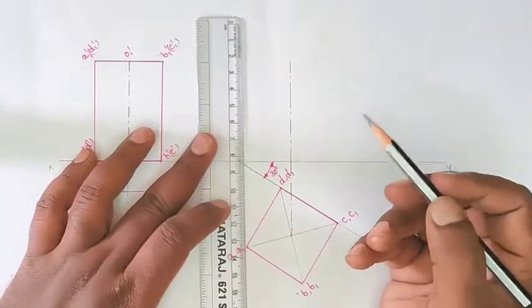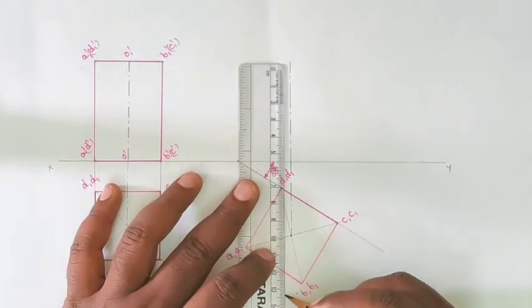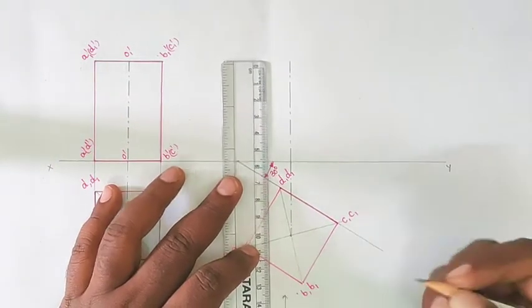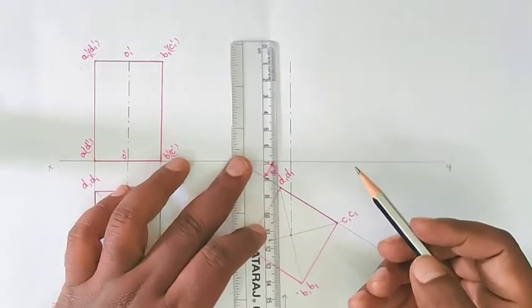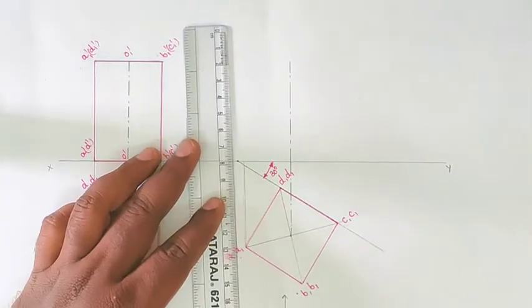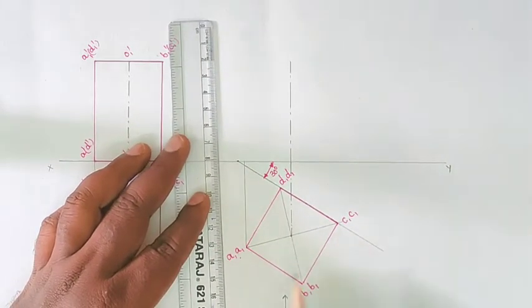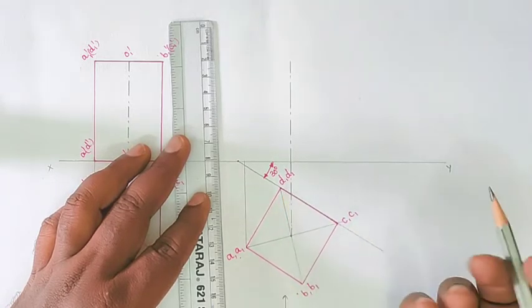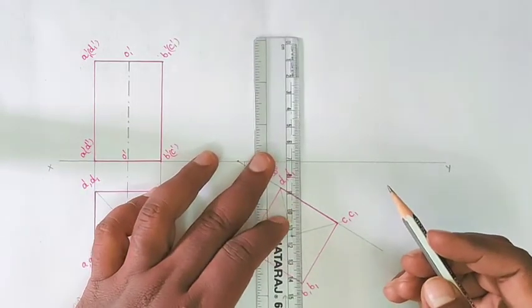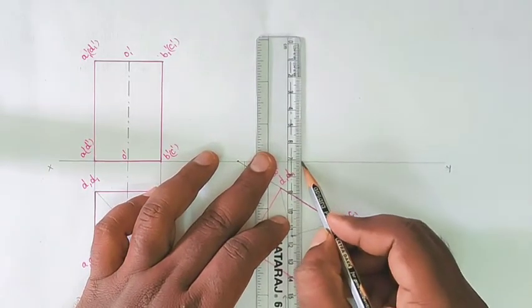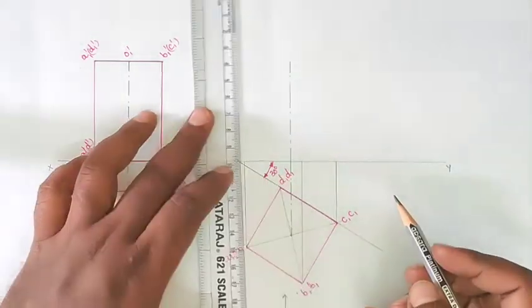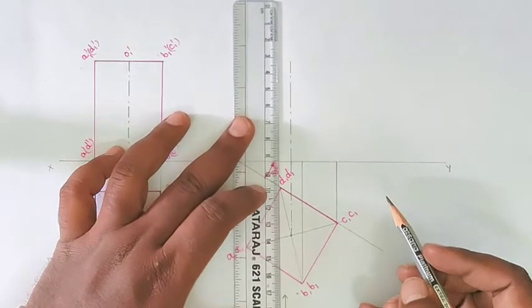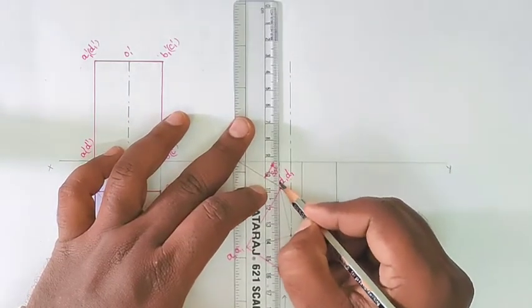After drawing the axis line, this is the direction of the front view. Now from the points on the top view, we will draw the vertical projection lines. Whenever you view the object from the downward direction, points A, B, C and A1, B1, C1 are visible, but points D and D1 are not visible. So you can locate them using dotted lines because they are invisible. From D, D1 we will get the dotted lines.